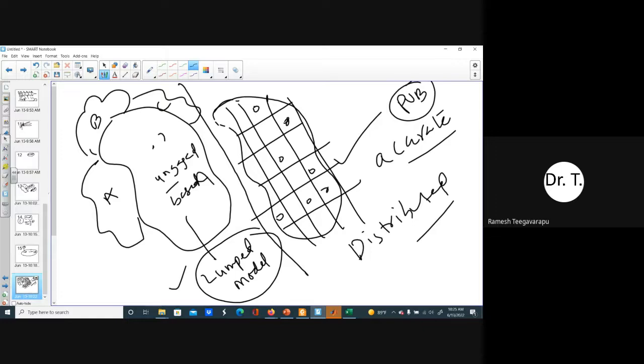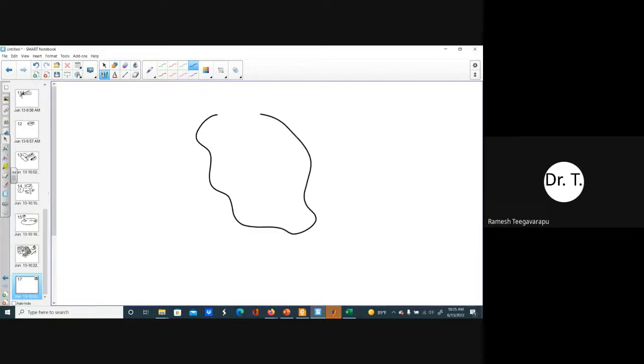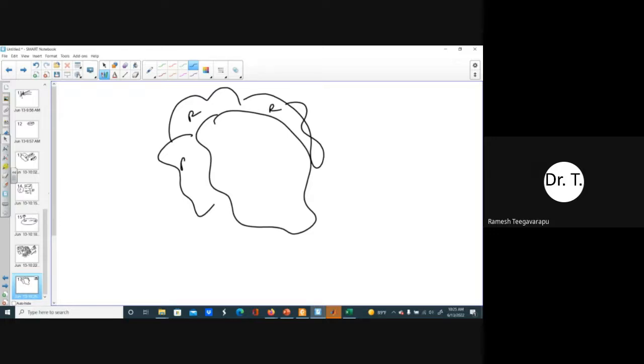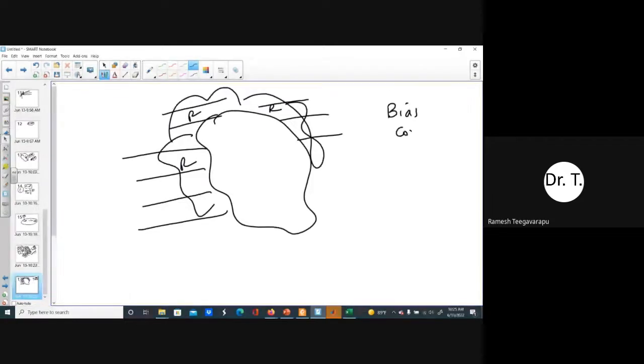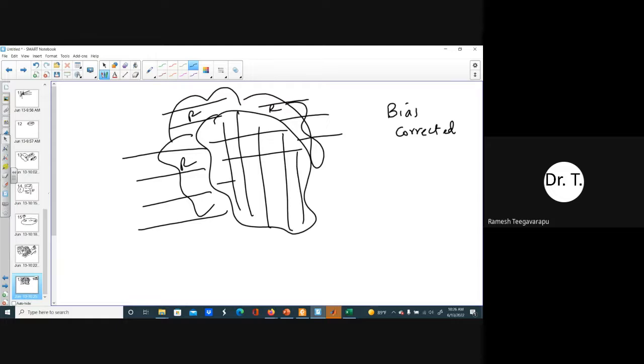But if, for example, we're looking at a basin here, and there are rain gauges here, here, and here, the satellite-based products can be adjusted based on these rain gauges. That means they can be bias corrected. So you bias correct the satellite-based products, and then, since they are bias corrected, you can have some confidence in applying satellite-based products in this ungauged basin.